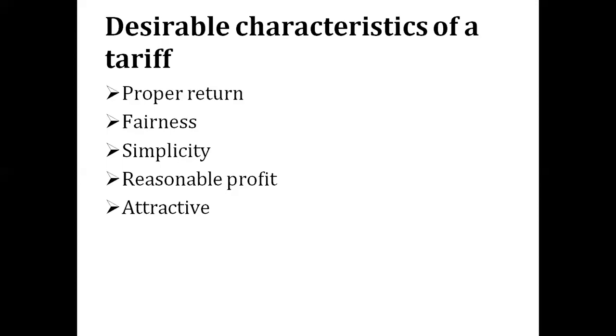It is given that increased energy consumption spreads the fixed charge over a greater number of units. Thus, it reduces the overall cost of producing electrical energy. Similarly, a consumer whose load condition does not deviate much from the ideal, that is, non-variable, should be charged at a lower rate than one whose load condition changes from the ideal. Means a constant load consumer must be charged at a lower rate.